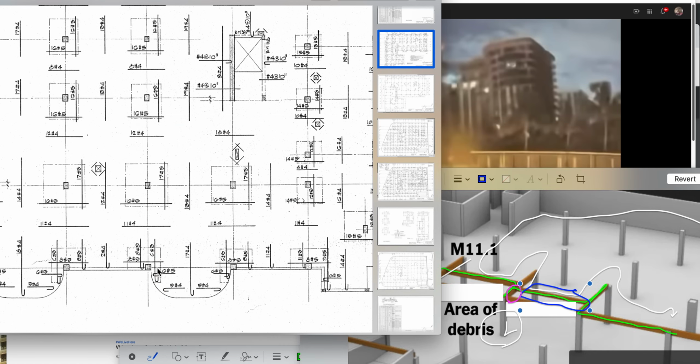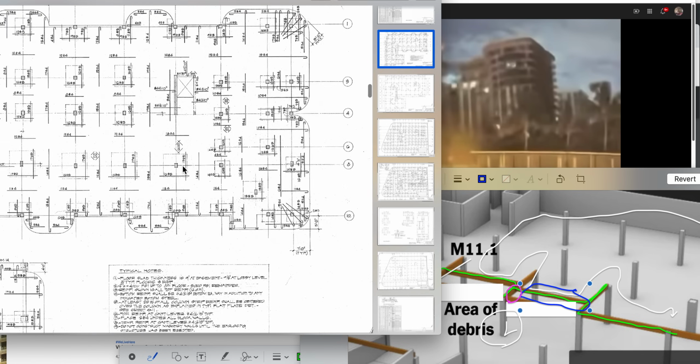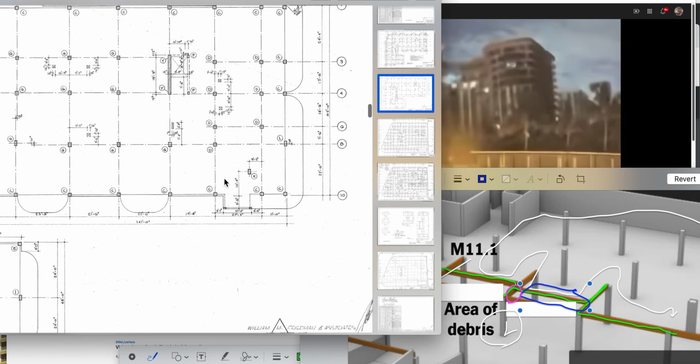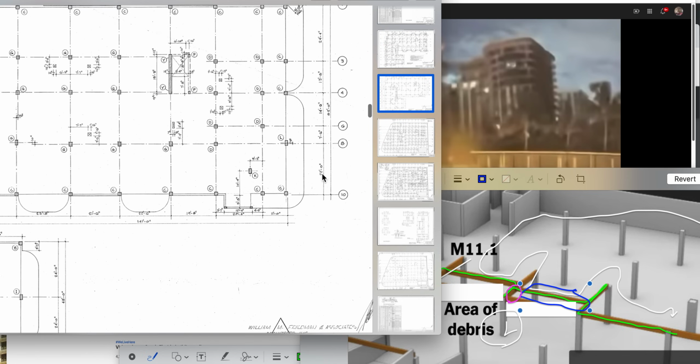So now I think I've got you up to speed to help you understand that we only got 3 sides of a critical shear area to support a large 20-foot span, and then there's a greater span there. You know what? I think there's a measurement here. Right there, there's 22 feet.